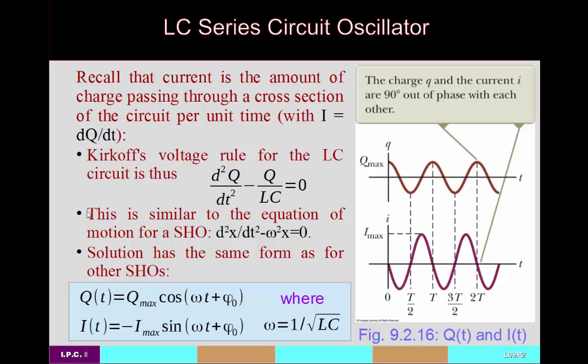If you add a resistance to this circuit, it gets more interesting still, but I don't really have time in today's lecture to really cover that. Basically, what you end up getting is a damped oscillation, where the damping is from the resistance. Basically, you would add a term in here that looks like an I times R, and then again replace the I with dq dt.